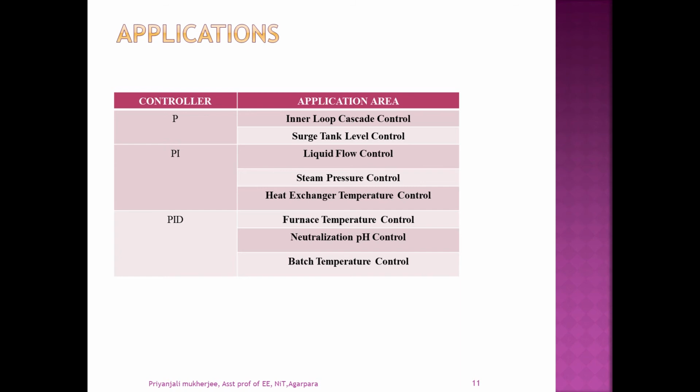The P-only control alone is unsuitable as it is unable to adequately track the set point. The PID control routinely leads to excessive variability due to the noise. Whereas we can use the PI control because it delivers improved set point tracking and does not subject instrumentation to unnecessary wear and tear.